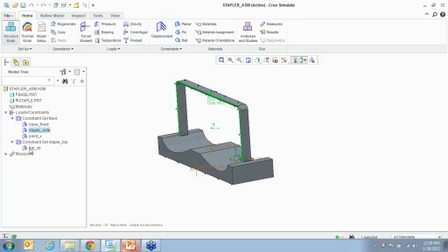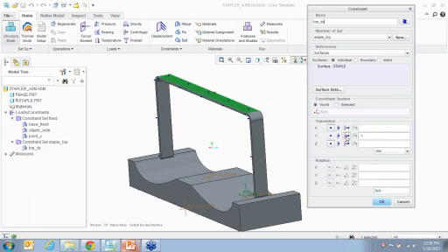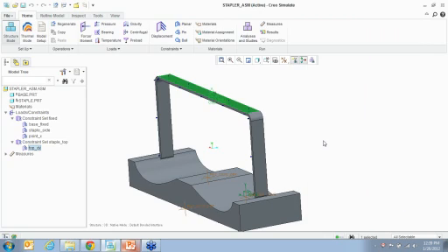Now, I'm putting a constraint at the top. This is another thing that I want to show you. You can use something called a prescribed displacement. So in here, I'm saying it can only move a maximum of -1. So it's going to go down. Okay, that top surface. So that's a constraint which is going to actually act like a load.